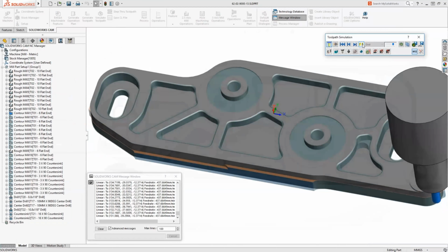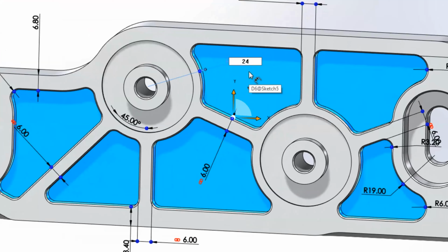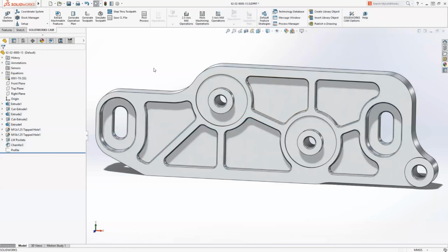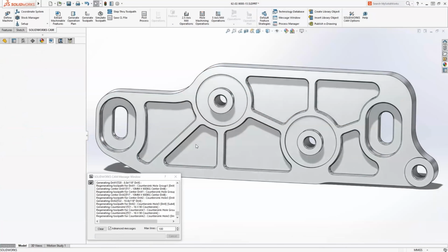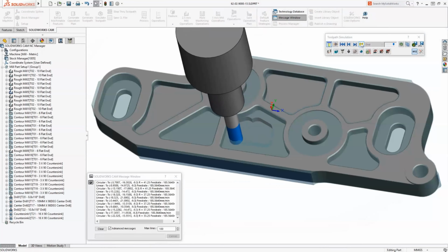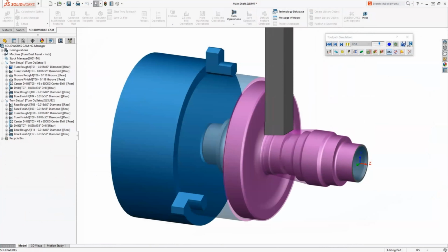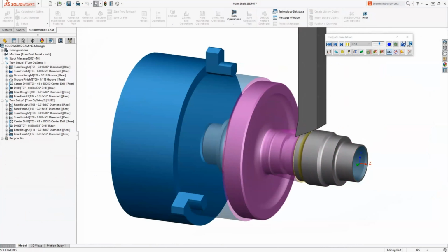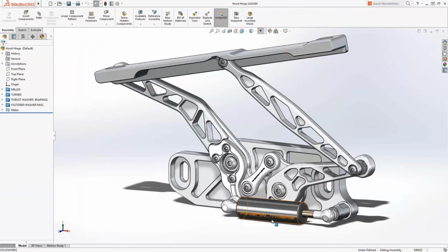And also it has a capability of machine learning. So what it entails is if I, as a user, like a specific type of work cycle, I can tell the machine, this is what I like, and it will recognize in my future designs, in my future CAM processes, that this is my type of machining, and it will use those cycles again. Then I can populate this back to my CNC machine, and I can do my material cutting.